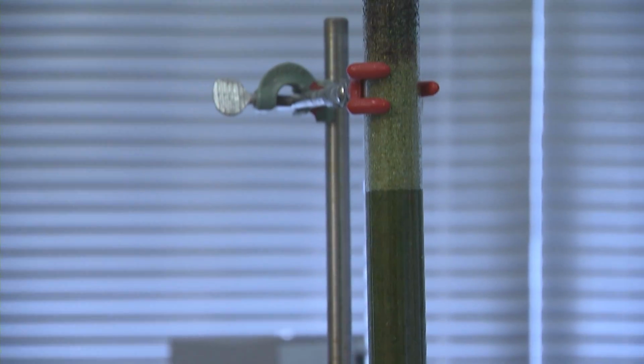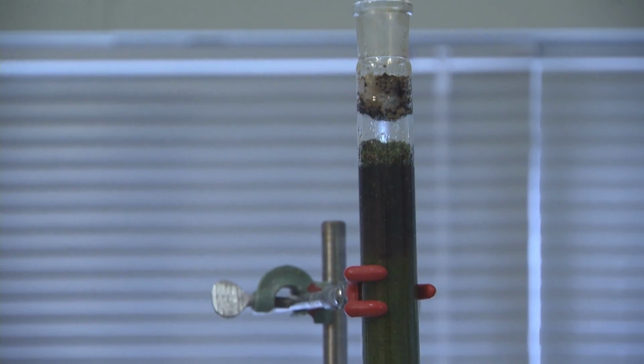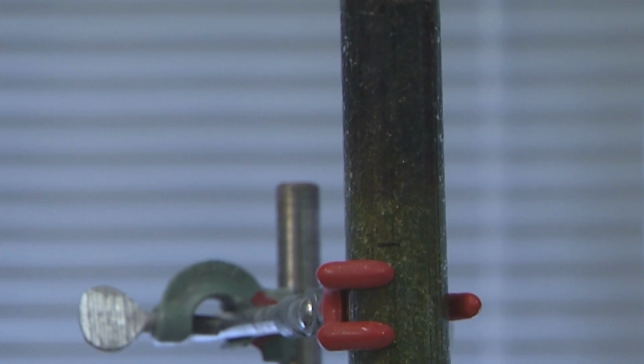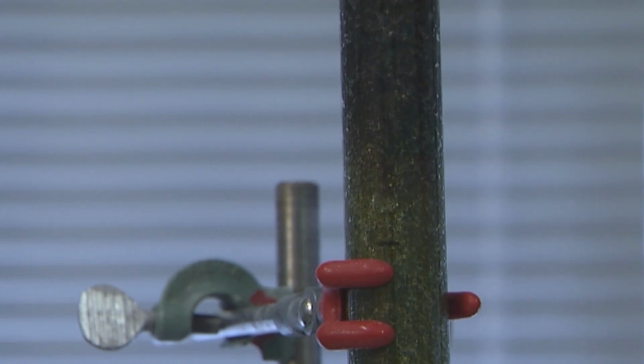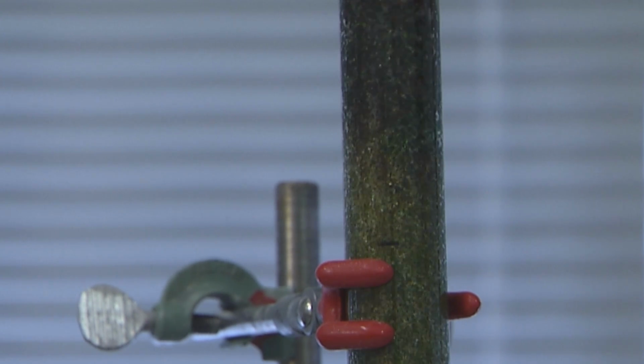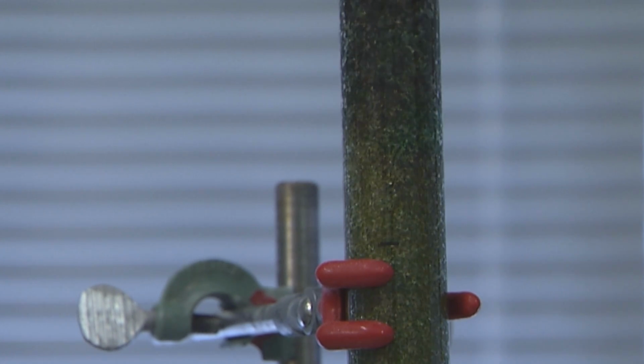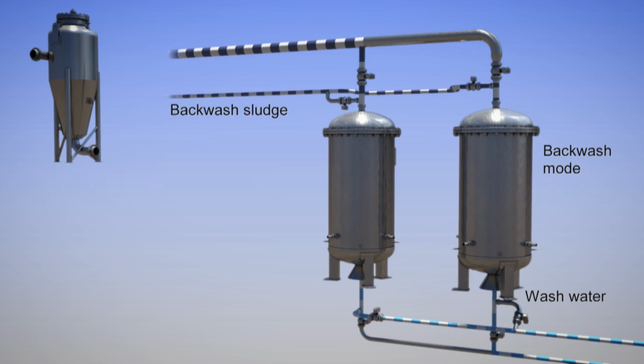Another feature of the flocculated SORBFloc is that the encapsulated material is non-sticky, so that the filter media is easily and fully regenerated, simply by periodic backflushing with unheated, clean water. The recovered contaminants with the wash water are then recycled to upstream of the primary separation in the SORBSEP unit.